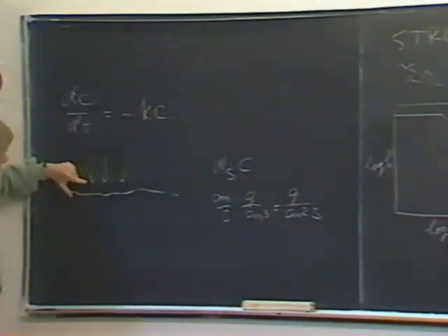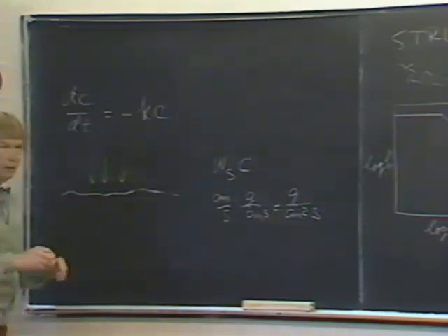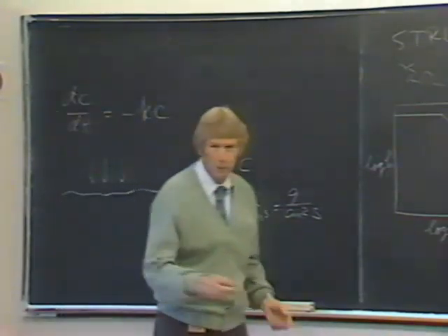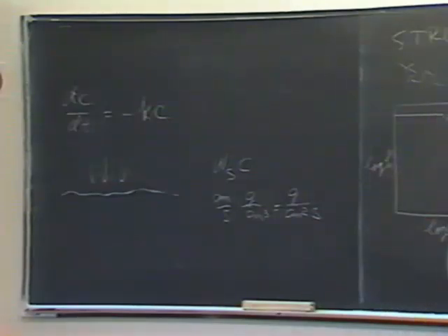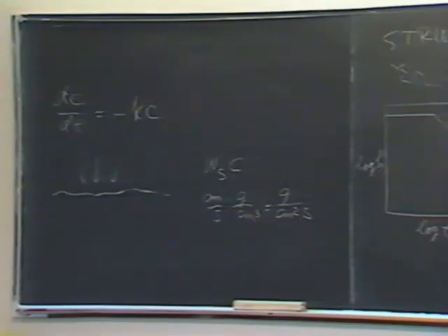In this flowing water, however, the particles that go to the bottom may not stick. Remember, we talked about a viscous layer last quarter. Some of you weren't here, so I'll describe it again. In open channel flow, where momentum transport is turbulent, we can describe the velocity profile in terms of a logarithmic velocity profile. Looks something like that, Z against the velocity.